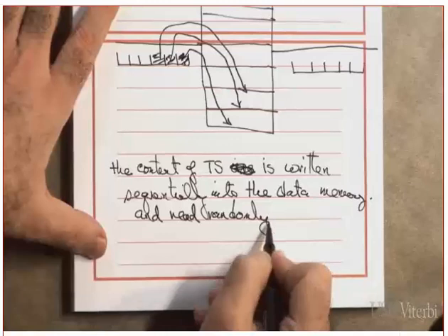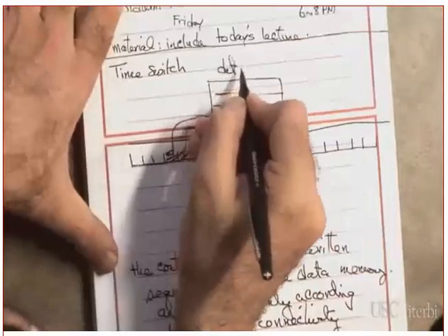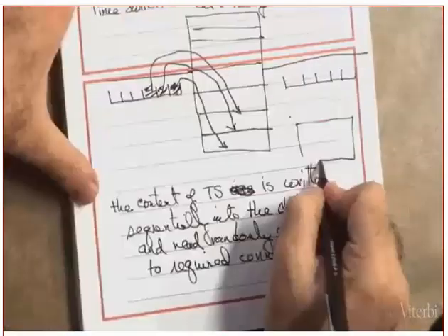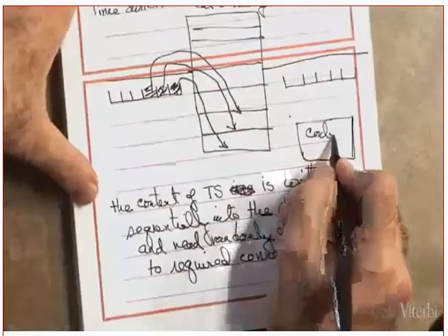How about number 3? Can I read it here? No, I cannot read it here. Why? Because this one has already gone. This is time slot number 1. It has already gone. So where will this one be switched to? To the first time slot in the next frame.